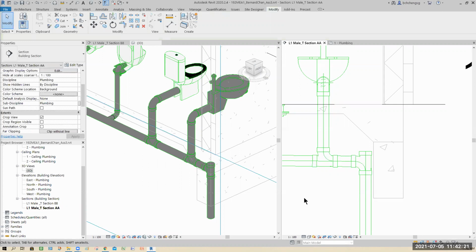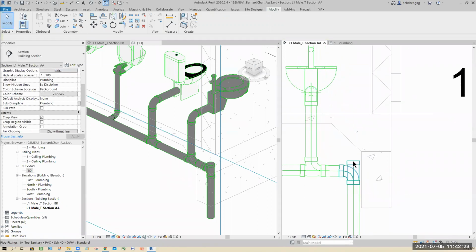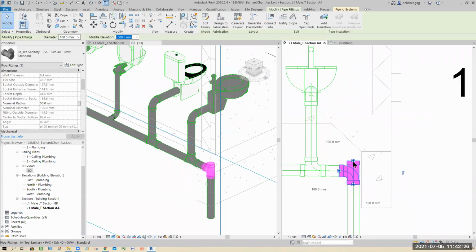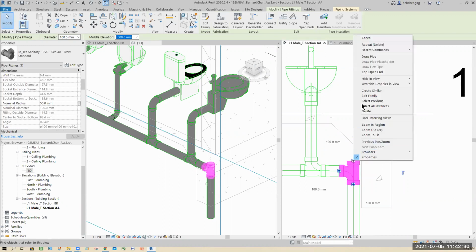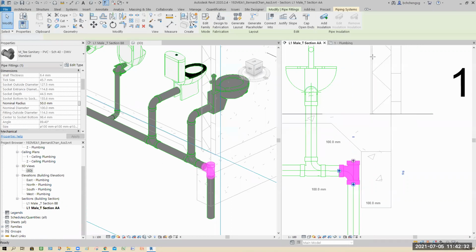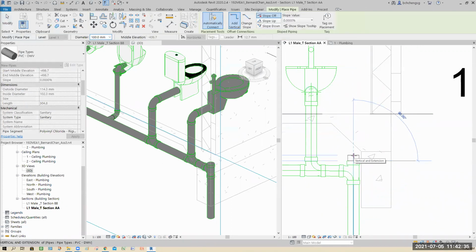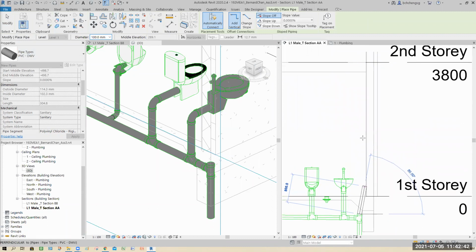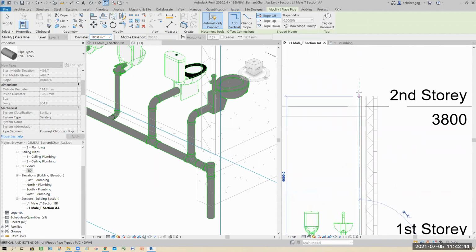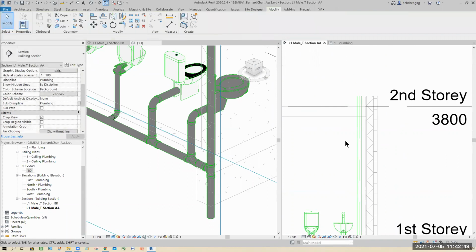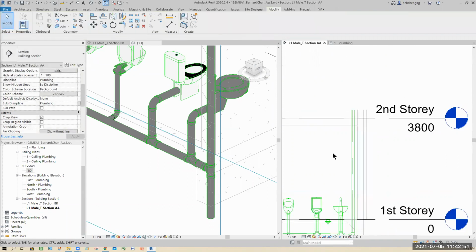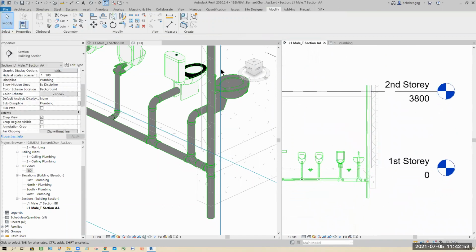Okay. So from there, you select the fitting, and you see there's a connecting point. Right click, you say draw pipe. When you select from PVC and draw pipe, they automatically become PVC. Then you just draw above, it can be seen like this, because of your section view. So temporarily we keep up to here.